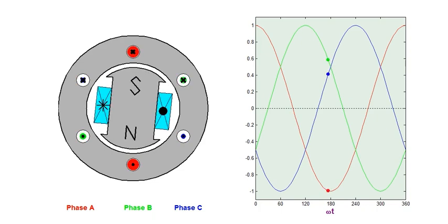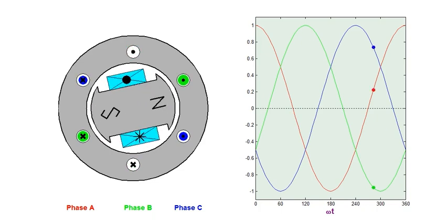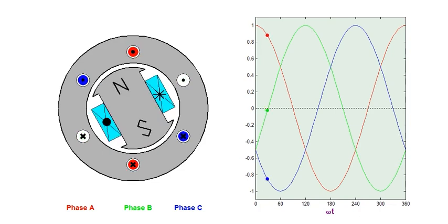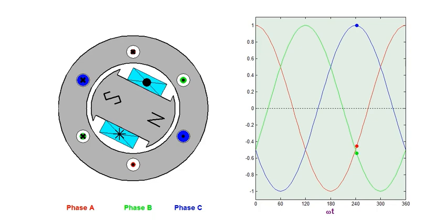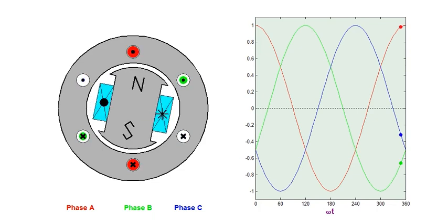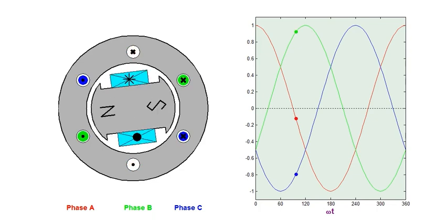Something must overcome the inertia of the rotor before it can get going. In addition to that, the speed of a synchronous motor is tied to the frequency of the three-phase power supplying it, so the speed of the motor isn't very easy to change. Synchronous generators work much the same way, just in reverse.